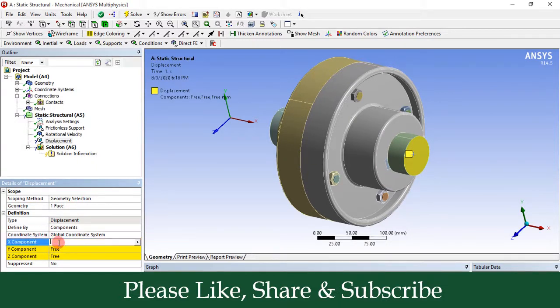Then I will enter here x component of displacement as 0 and others will be free. Okay, so I have applied the displacement on this end, one end of output shaft, so that its displacement along x axis can be restricted.